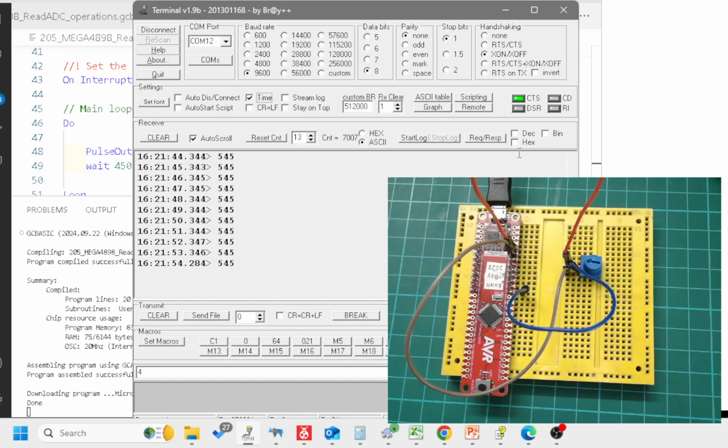But they are there. You can look at the assembler, and you'll see that the registers required to set up the timer have been set up, that the global interrupt flags have been set up, the timers have flags or interrupt flags are cleared, but that is something that is documented, and all we've done is just captured that knowledge inside the back-end program, and that happens automatically.